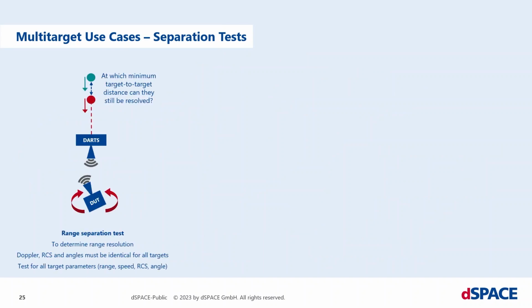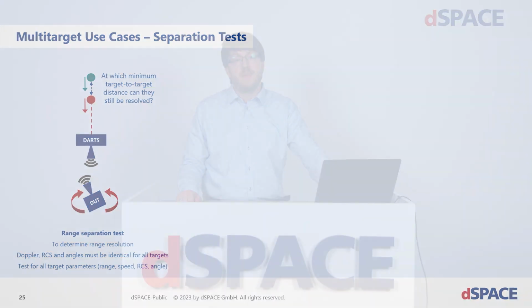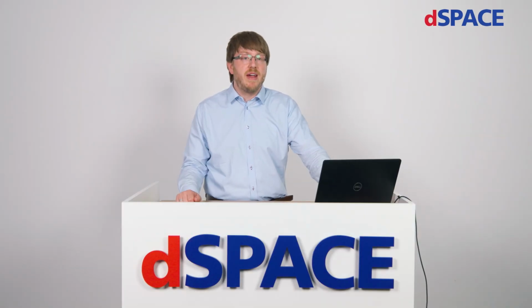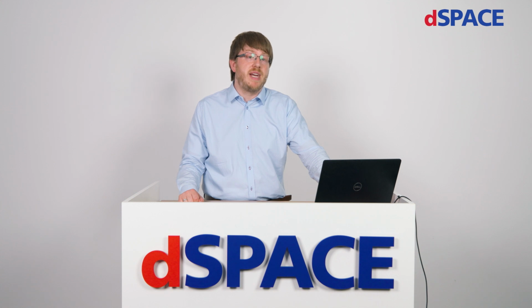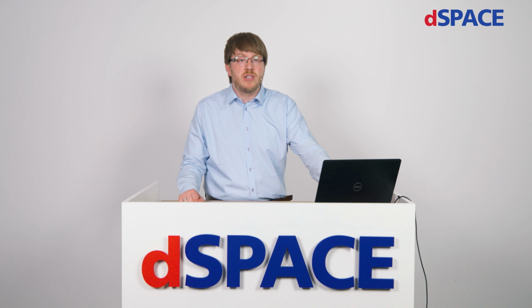The range separation test determines the range resolution of the radar sensor. The basic question that has to be answered with each test is, at which minimum range from target to target can the target still be resolved by the sensor? This has to be tested for a range of different target speeds, target sizes, and also over the whole field of view of the radar sensor. This is to make sure that the specification holds in every case.